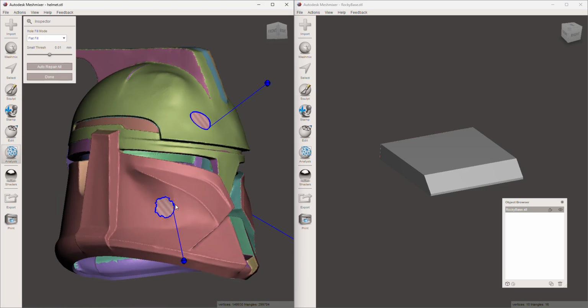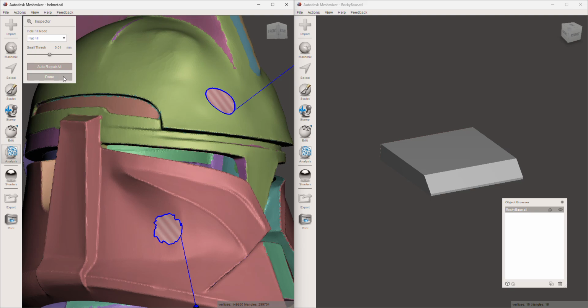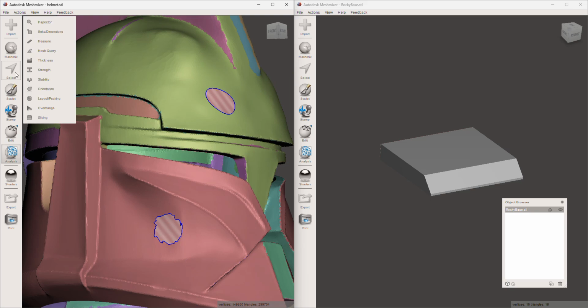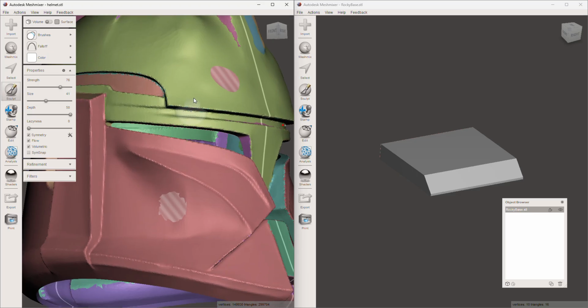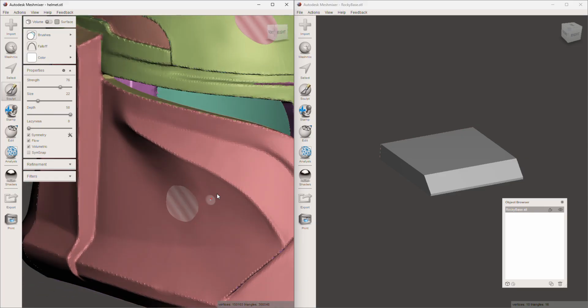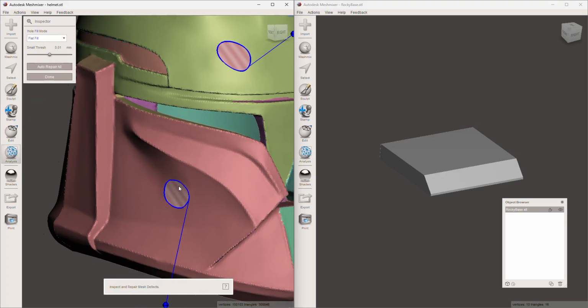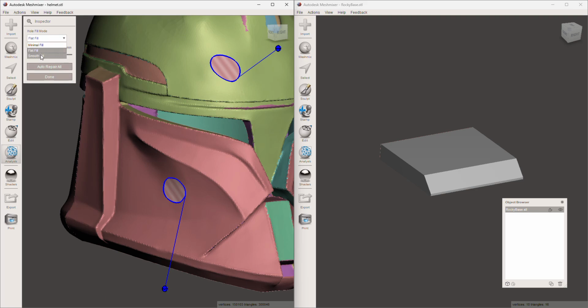But sometimes it'll show you a red circle here and it says, hey, that needs work before I can fill it in. So in that case, what you do is, again, another super critical tool, especially for armor like I do: go in here, hit Shift, and smooth out these edges. I'm just slowly shift clicking. Now I've got a nice smooth circle that I can go analysis, inspector, and it'll mesh better. We'll do smooth fill, auto repair all, and boom, there it is.